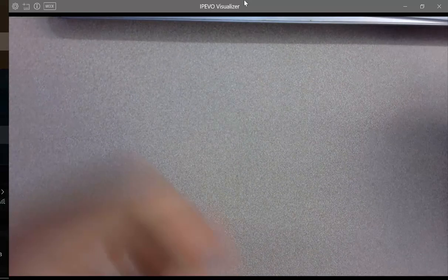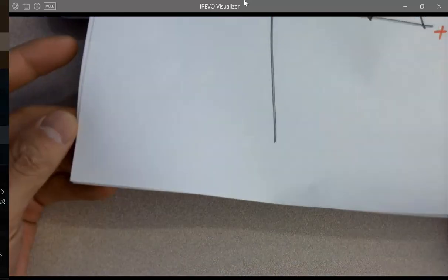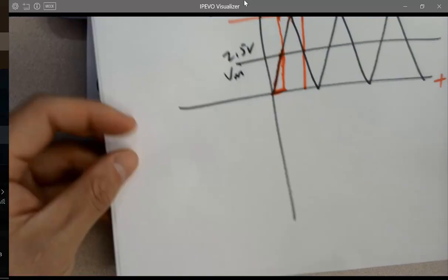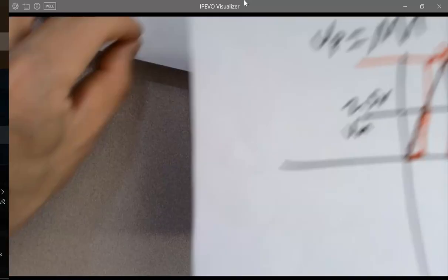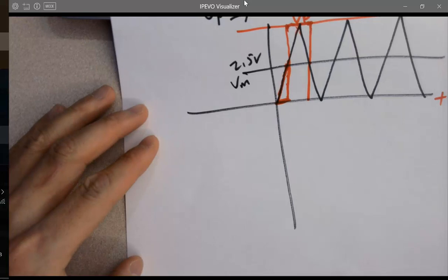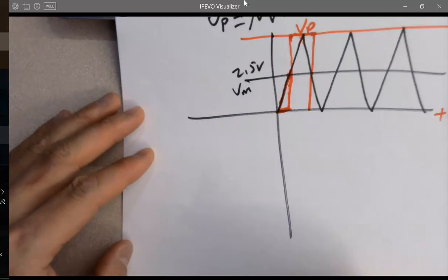That makes sense to everyone? Kind of. Okay. This will clarify a lot of things, right? Because you got confused about why it performs like this sometimes, why it's amplifying an analog signal. Because you don't have any feedback, that's why it's a comparator instead of an amplifier.